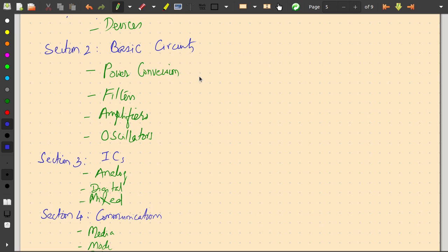So when you want to choose from the whole spectrum a particular band of frequencies, then we have specialized circuits which are called filters. We have basically four types of filters: low pass filter, which allows low frequencies to pass through; high pass filter, which allows high frequencies to pass through. We have band pass and band elimination. And the names tell what they do.